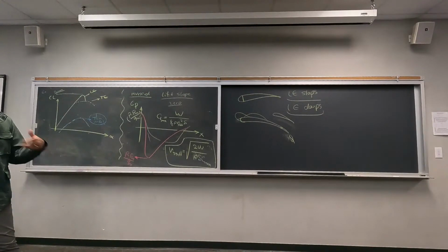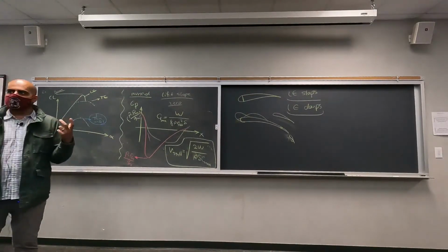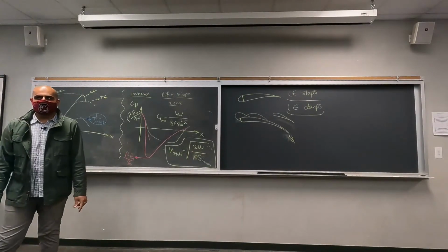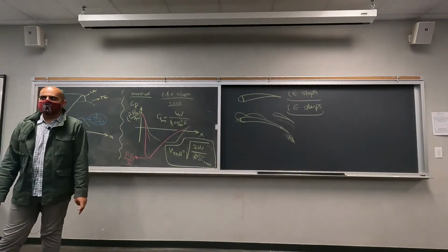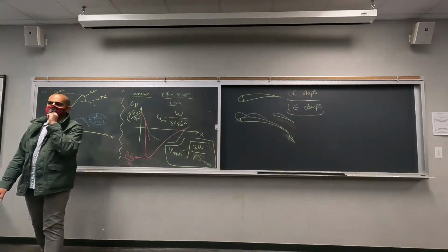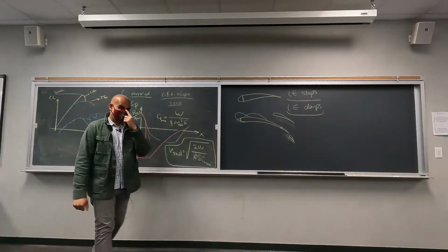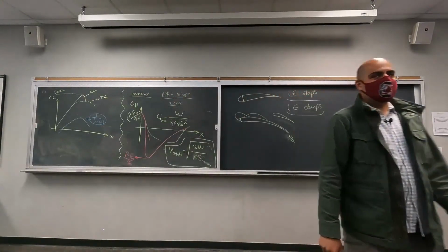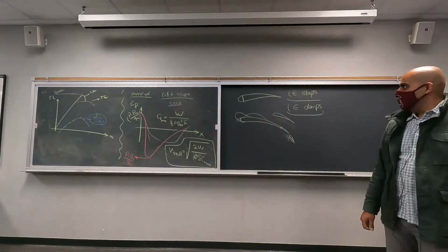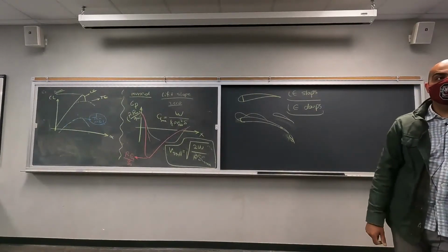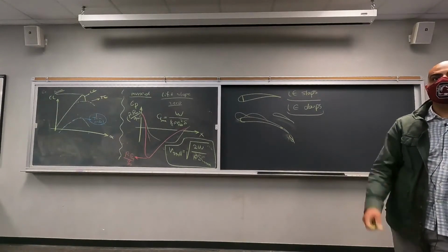But think about it this way: how would stretching the airfoil change the flow pattern? How would that reduce the flow separation? It would increase it, would it not? So you need to reduce the chord? That's one way of looking at it, but then you are reducing the span area, which means you're going to have lower lift, total force, right?